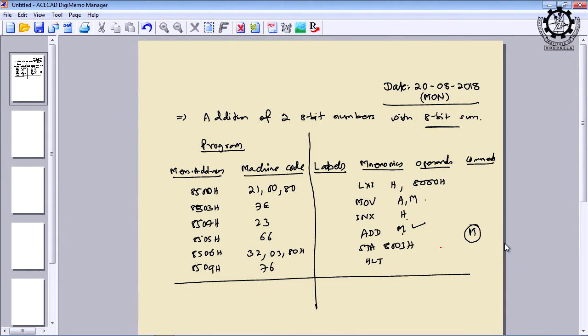Okay. But as far as the practical laboratory class is concerned, this left part is important. Why is it important? Because we have to store this program starting from a memory location address from where the execution will begin, and for that you have to know which locations are reserved for the system routines. And already I have told you, from 0000 to C000 try to avoid these memory locations because these are storing the system routines and implemented in the form of ROM, PROM, EPROM, etc. Okay. So, 8500 I think is a valid address from the practical point of view, right.